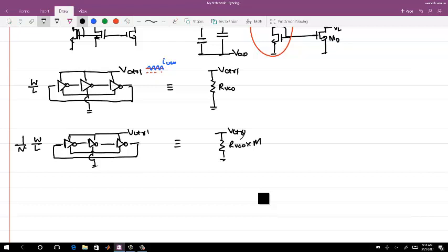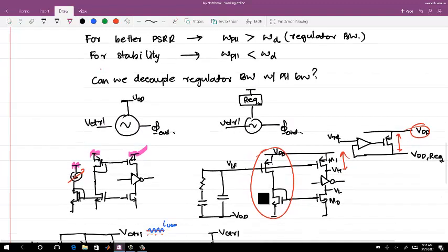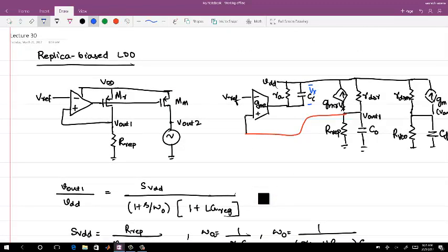But the actual problem is that you will still be having ripples on the supply, on the control voltage itself. Now the question is whether it is good or bad, which you can check. Surely, if you are having a ripple in the system, your loop is always working. It means you will see some more glitches, not that it's unstable. The loop is stable, but for incremental changes you will see ripples at the control voltage. If you use a VCO, the same ripple will get translated, and depending on the multiplication factor, it is again getting multiplied. It's not a flat DC voltage if your frequency is not changing.